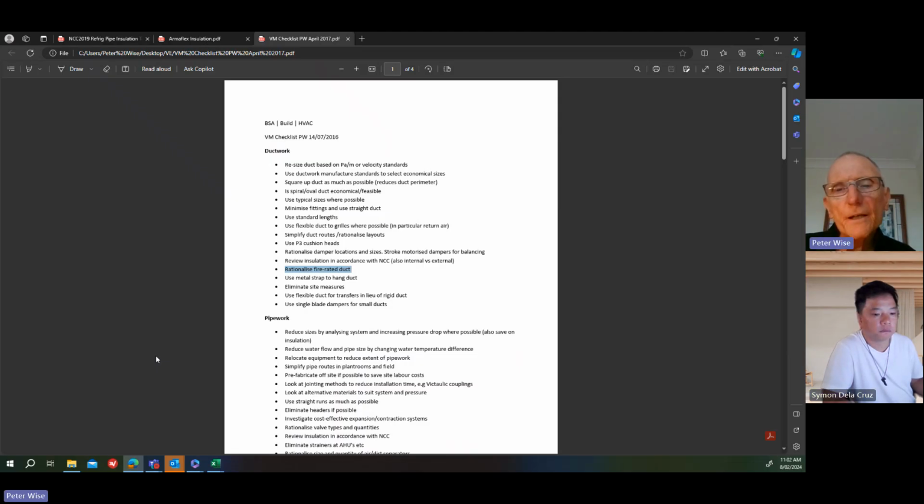And if you work on a small building, you don't need to worry about it because it won't apply. But when you get into more complex buildings or multi-story buildings, then you do have to consider the requirements of Section E. It talks about stair pressurization, smoke spill, all of those things, depending on the type of building and the height.